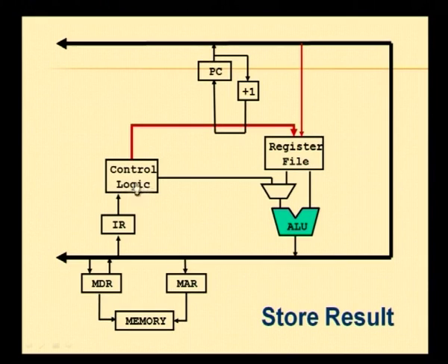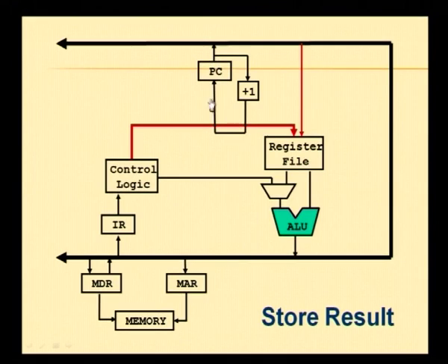We will look at details of that when we look at the complete data flow in detail in later classes. But right now, with this picture of just a few registers and the ALU and the control logic, you should get some idea of what is actually happening inside the processor. Now, there is one more step here. Remember we had incremented the PC. So, to access the next instruction, all we need to do is that the address is already available at the fetch. So, you have to now initiate the next fetch.